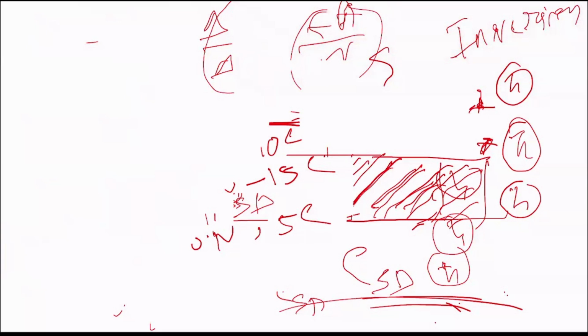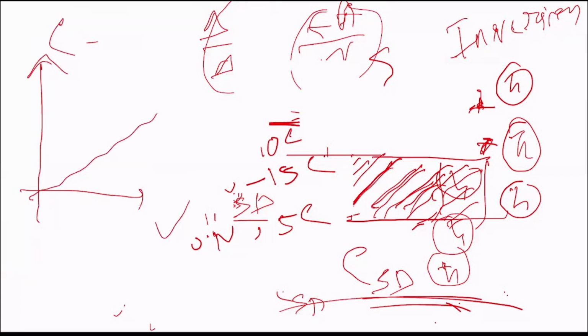So you basically apply something like this. If you want a C-V graph, you increase the DC voltage. You also apply what? A little bit of AC voltage, so you can measure the change of charge with it. So basically, you are applying both. And that's how you know at a particular voltage what the capacitance is. Are you guys with me so far?